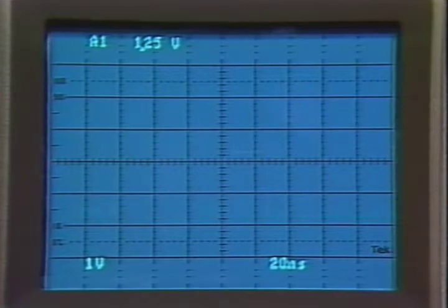And here's the second case. A narrow, fast-rise pulse with a low repetition rate that was invisible on the normal high-speed oscilloscope. Note the sweep speed. Why does this instrument display those pulses when other scopes won't?